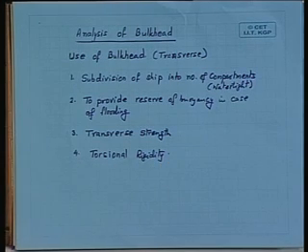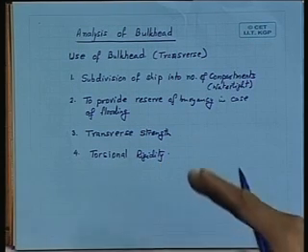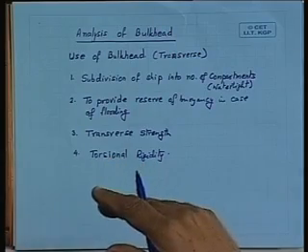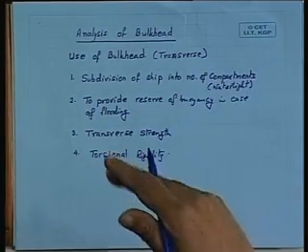That means, apart from the direct in plane stresses being transmitted to the bulkhead, there is an in plane stress also. This in plane stress is basically the shear stress too, because of the torsion some shear stress will be generated. So, this is also subjected to, apart from the in plane direct stress, some sort of in plane shear stress.